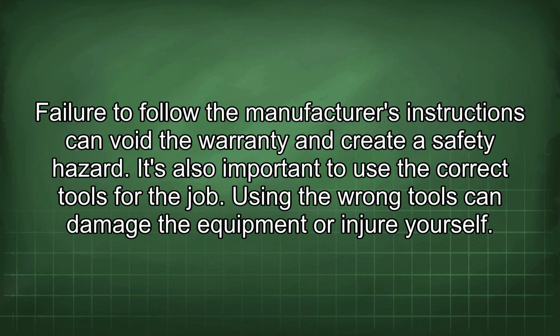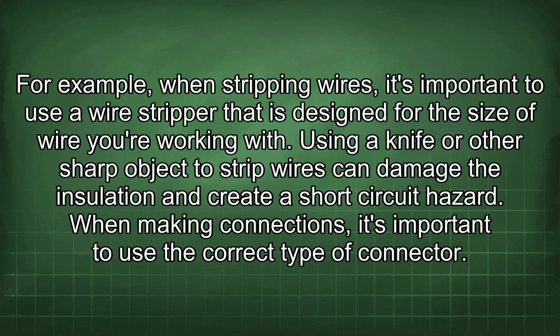It's also important to use the correct tools for the job. Using the wrong tools can damage the equipment or injure yourself. For example, when stripping wires, it's important to use a wire stripper that is designed for the size of wire you're working with. Using a knife or other sharp object to strip wires can damage the insulation and create a short circuit hazard.